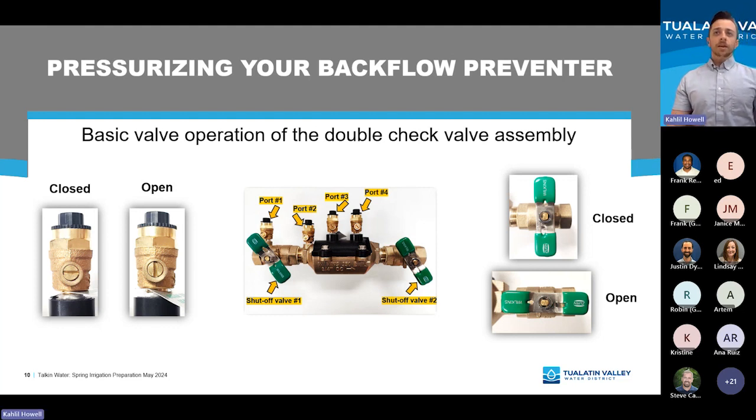And if you're missing a shutoff valve handle, which sometimes happens with a rusted shutoff valve, you can often get a crescent wrench down in there onto what remains of the shutoff valve to operate it, but it could be a time to consider some maintenance to a backflow assembly missing shutoff valve handles.